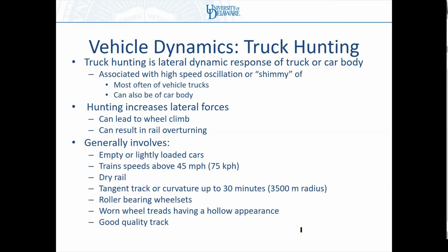Now, truck hunting, and again, you saw some really nice videos of hunting. Hunting is a lateral oscillation of my axle set, which is going from side to side as it goes down the track.